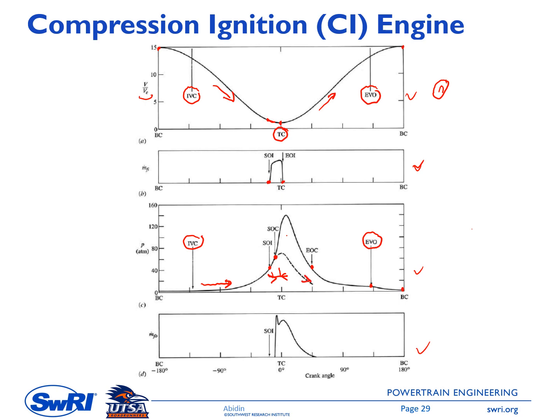And the last feature here is showing the profile for the fuel combustion in terms of the burned fuel. Okay, so this is the SOI, and then we have SOC here, and this is the profile for the release of the heat. Okay, and this usually follows the rate shape of the fuel, and then we will have a main combustion here, and then at the end we don't have the fuel anymore, and this is end of the combustion.